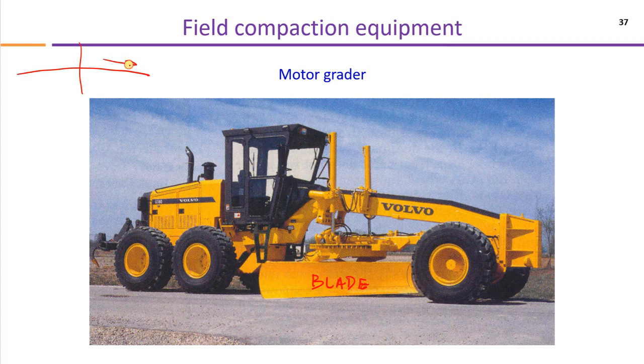So these are the slopes. If this is the center line of the highway, then how are we going to achieve this slope? This is with the help of these motor graders. These graders are going to displace the soil, and they are going to make the desired slopes.